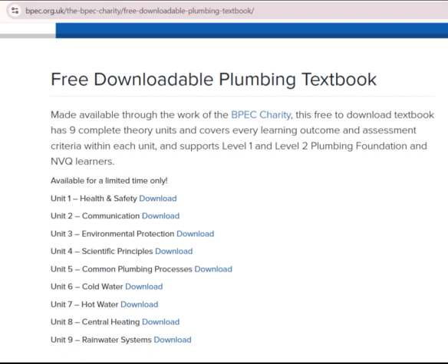The principles of the pressure jet, atomizing, burner. Pressure jet burners work on the principle that the oil must be atomized and mixed with oxygen before the oil will ignite. Atomizing burners have an electrical fan to introduce the air and a fuel pump to push the oil to the nozzle. The fuel flow is controlled by an electrically operated solenoid valve.